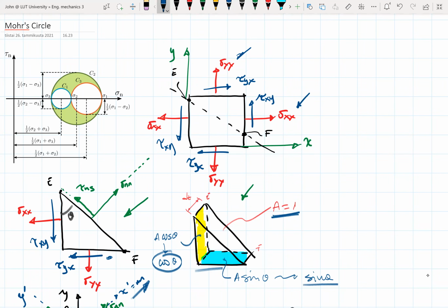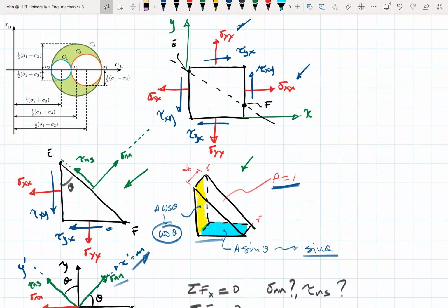This Mohr Circle would allow me to find the other stresses if I rotate that cube or orient it on another Cartesian coordinate system differently, and it gives the maximum stresses that I could find. It's a pretty graphical and beneficial tool, in the sense that in one glance I can see the maximum stresses without iterating with the formulas to find the maximums or minimums of stresses in a point of a body.